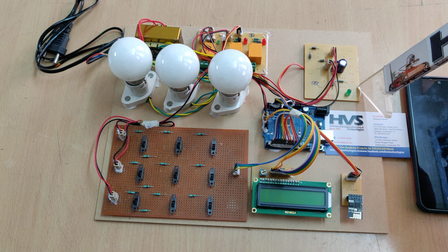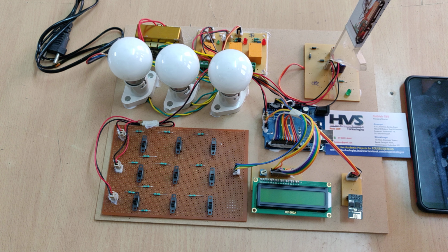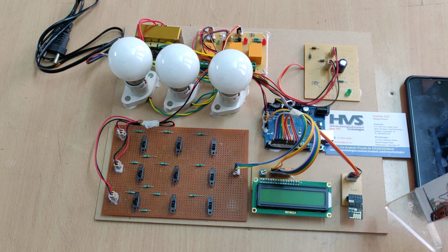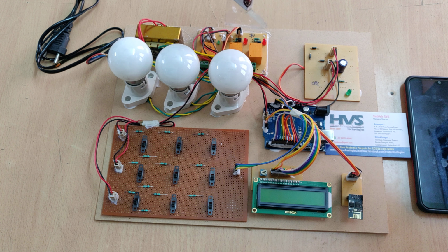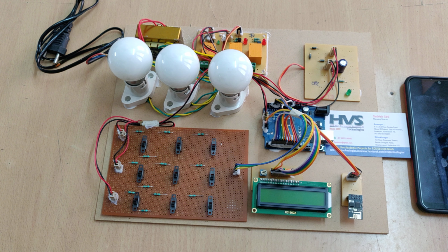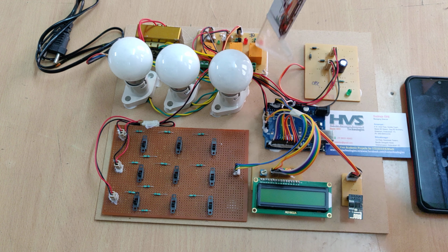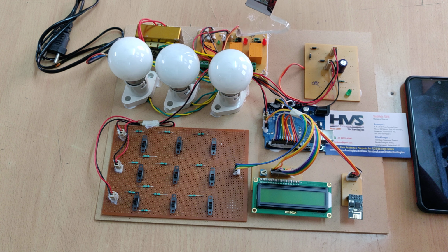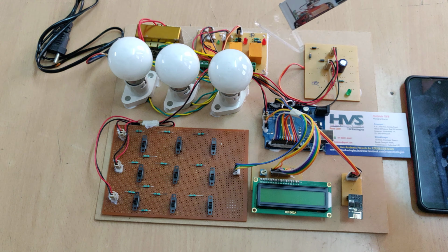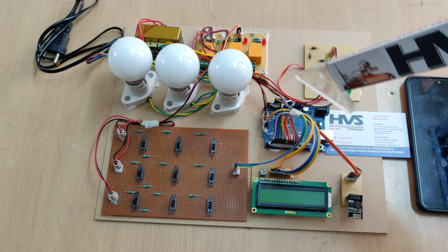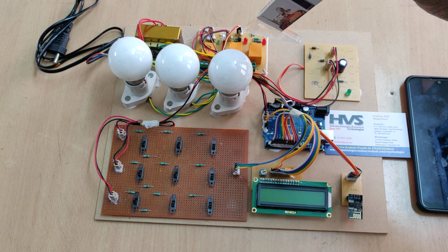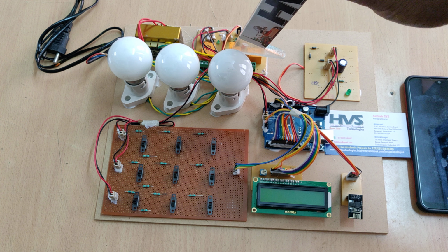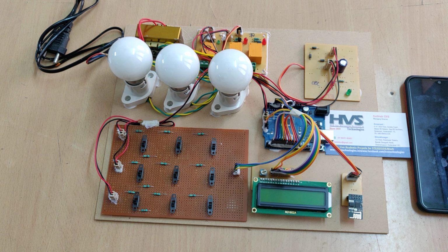voltage. Coming to this regulated power supply, there are 4 diodes that act as a bridge rectifier, and after this capacitor we get the pure DC voltage. Coming to the relay boards, on this relay board we can see the LEDs. Those LEDs show us the on and off status of the relay. We can also see 3 transistors on the 3 relay boards. This black one is a BC547 transistor. The switching flow is: the Arduino UNO triggers the transistor, the transistor triggers the relay and LED, and the relay triggers the bulb. So this is the switching flow.